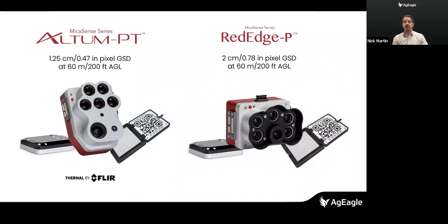If you went and produced a map with that shadow, well, guess what? There's going to be a big dark spot in the middle of the field. The DLS2 will adjust the camera settings on the fly, real time, so that you don't get that inconsistent quality in the same flight. So the combination of the CRP, which is the calibrated reflectance panel, plus the downwelling light sensor, which is the DLS2, add up to an extremely precise camera. It's almost a scientific instrument.